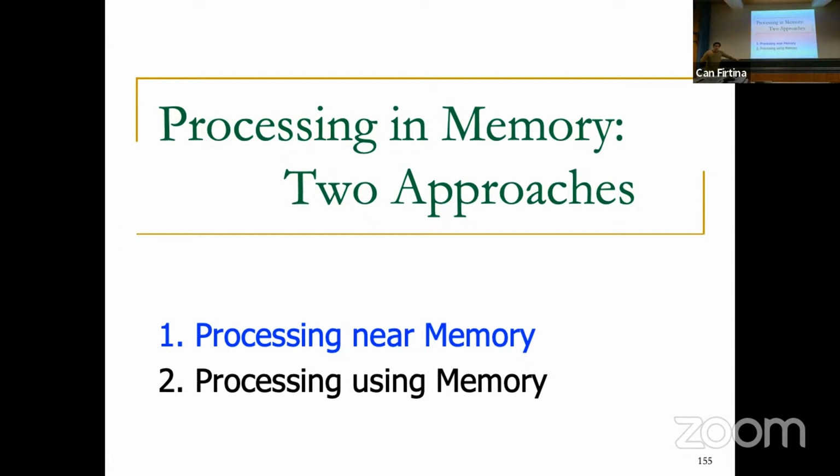The way that you normally access DRAM is by activating the whole row, and this row gets moved to the sense amplifiers, or in other words, when you activate the row buffer, each of the sense amplifiers in the row buffer senses the variation in the bit line charge, and they amplify that.